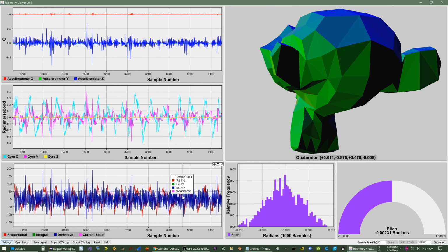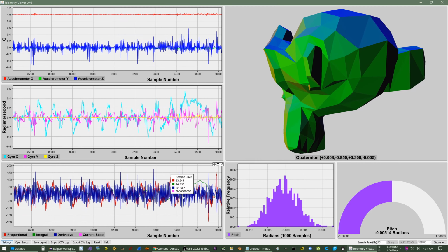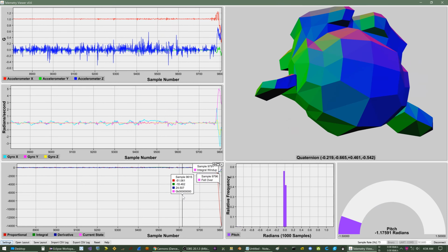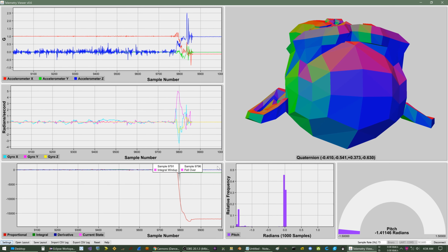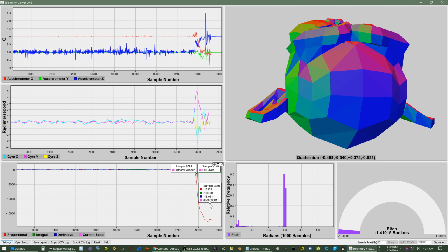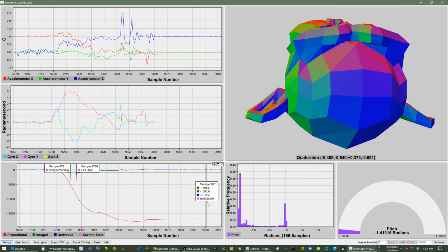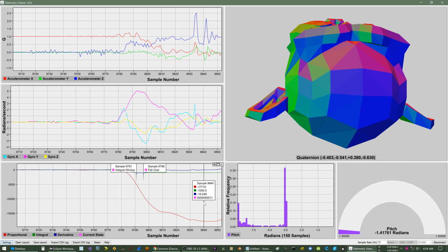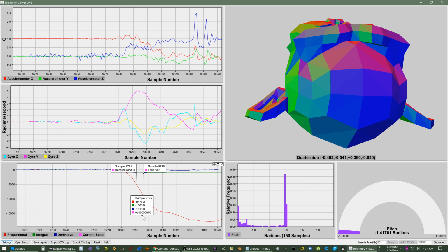I'm going to show how this works. If I pick up the robot and flip it on its back, we see a couple flags. Let me rewind. We'll pause time, and I'll zoom in by holding down Control and scrolling so we can see a little better. In my case, I have the firmware set up so that when the integral accumulator reaches either plus or minus 1000, it defines that as the integral windup limit, and it clips to that value.